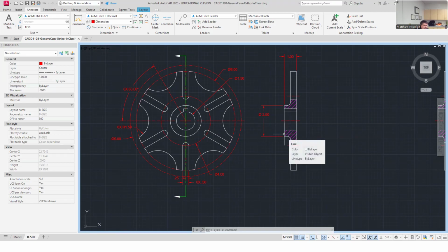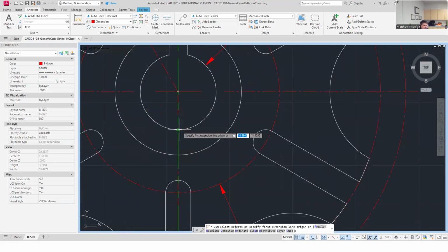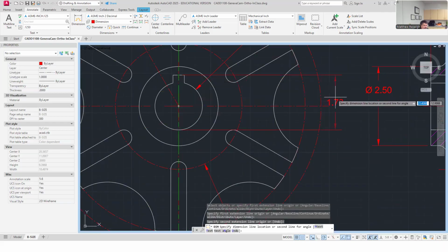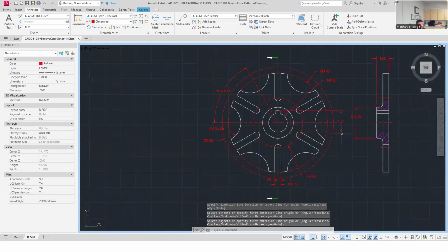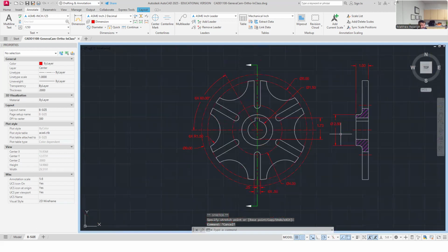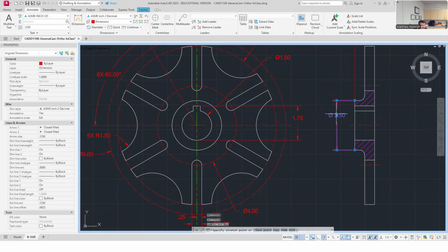What I do have is a keyway, to be dimensioned according to the ASME standard, which likes us to know the vertical in this situation. The way to do that, which we learned yesterday by doing the ratchet plate, is they want to know this to the highest height here as a linear dimension. I'm going to pull it off this way. And I'm thinking of it being in between views a little bit. Both of these are kind of in between my views. This one I need to pull way in. I don't need to be that far away. It's going to end up coming way closer.